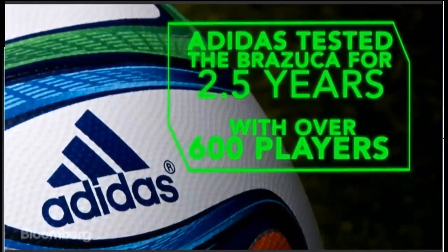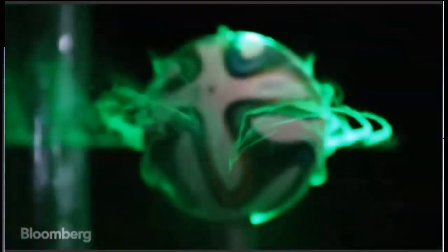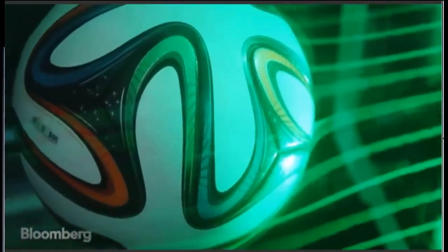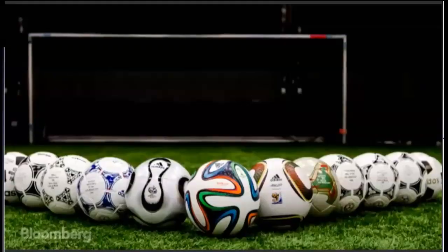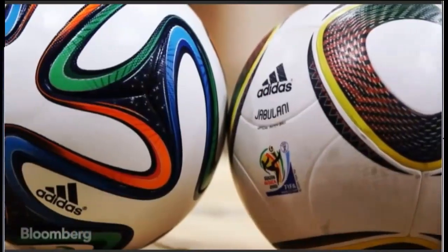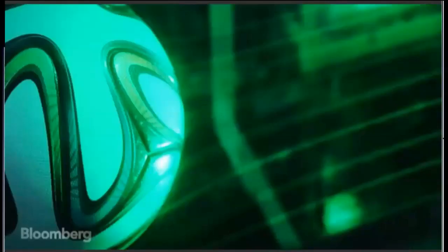What we're looking at with the smoke patterns is where that smoke leaves the ball, at what point along the surface. And when the position of that separation location changes suddenly, then that is the speed at which the ball will knuckle the most. I think the basic message for the players is that you'll see less of this knuckling effect. They'll find that it behaves more like the traditional ball, and I believe they'll be happier.